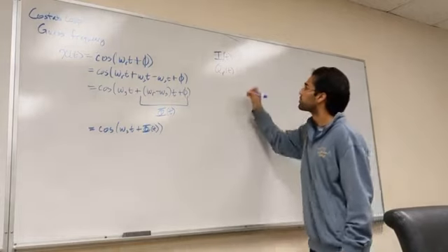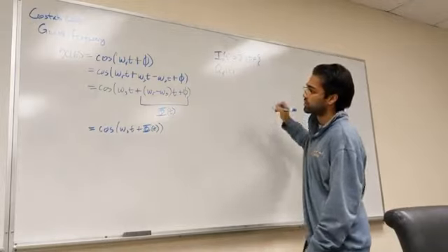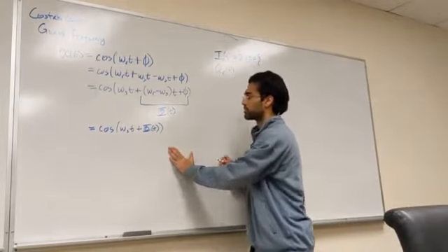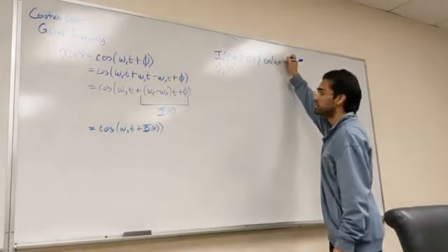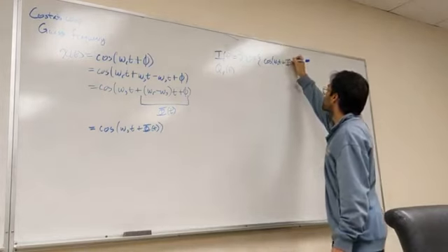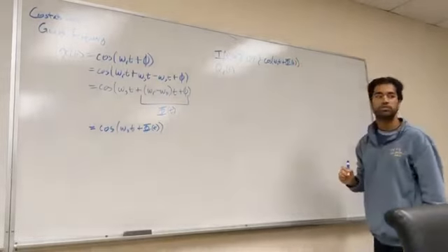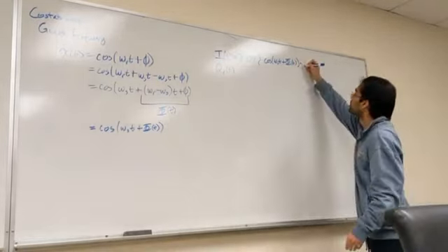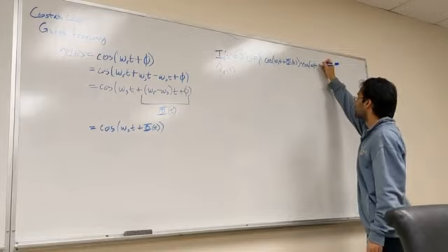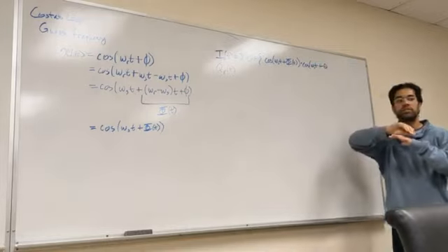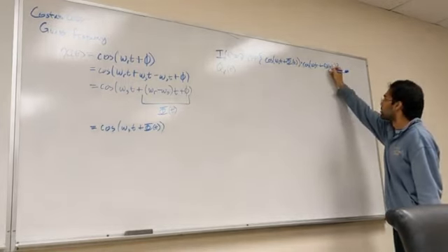We know this, so we can express our received information in terms of this: cos of omega s times t plus some arbitrary phase. Then for the in-phase component, multiply it by a cosine of omega s times t plus some additional phase component, and this is something we'll control.